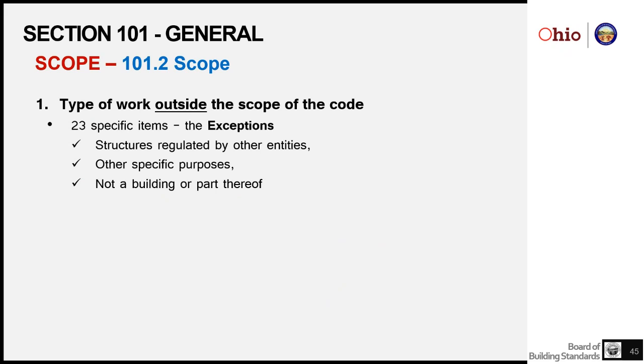However, if the owner does a change of occupancy in a manufactured house and turns it into a beauty salon or a barber shop or something like that, now the change of occupancy brings that structure into enforcement under the Ohio Building Code.